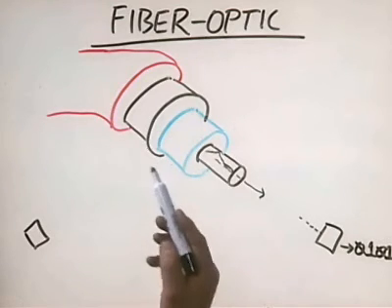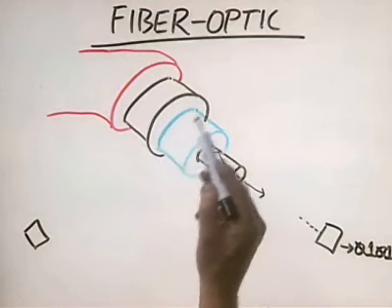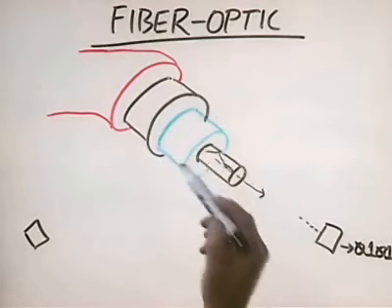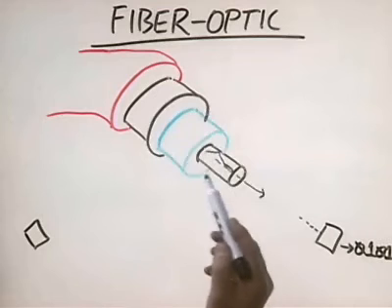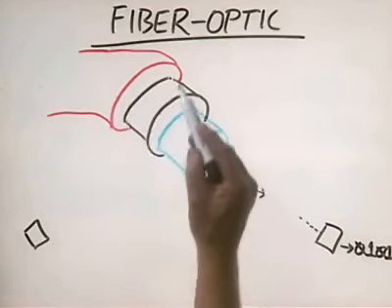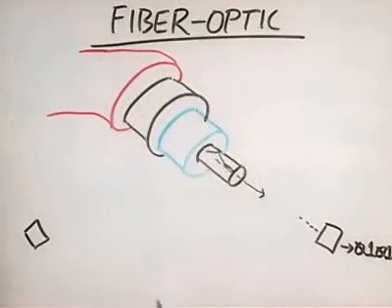Depending on the type of cabling you're using, surrounding the cladding are several protective layers that make sure that things don't get broken inside here. And then we have a plastic outer sheath that encases it all together. Fiber optic cabling has a lot of advantages. One of the key ones is the fact that it is completely impervious to electromagnetic interference. It doesn't use electrical signals, so EMI doesn't have any impact on it.